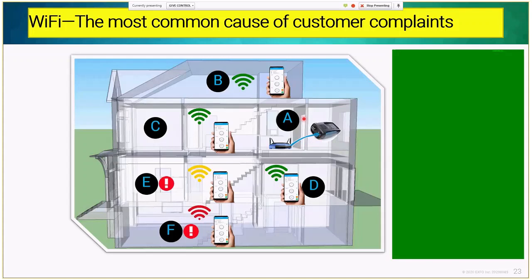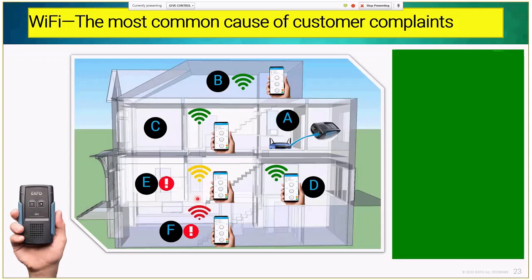You can do the acquisition near the router, go to the rooftop, do another measurement, check on the house, and perhaps advise the customer that he needs to place one more router, or needs a more powerful router for the service he wants. So not only does it give you the feedback that the service is well installed, but also the information if more hotspots are needed in the customer's house.